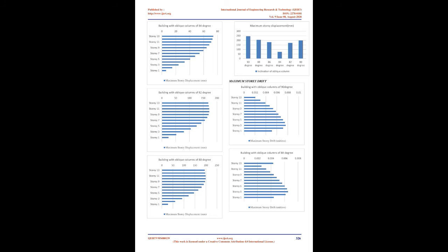There are computational advantages in using the response spectrum method of seismic analysis for prediction of displacements and member forces in structural systems. The strategy involves the calculation of only the utmost values of the displacements and member forces in each mode of vibration using smooth design spectra that are the average of several earthquake motions. This study deals with the response spectrum method and its application to various types of structures.